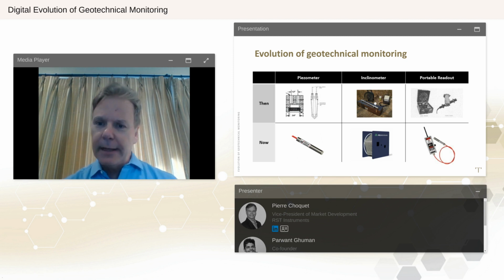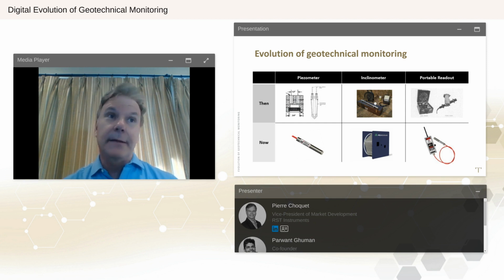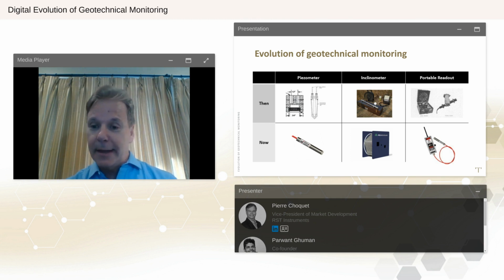Then in 1979, I became part of the monitoring team as a graduate student of the 13-kilometer long, 8-meter wide Frejus tunnel built in the Alps that was under construction between France and Italy. And I'll tell you that I would have liked data loggers to be invented at that time, because I had a good 50 vibrating wire concrete strain gauges and piezometers to read every day, in addition to measuring convergence across the 8-meter diameter using a tape extensometer. By the way, I would have also liked it if Excel had been invented at that time, because I had to plot all that data by hand for my daily and weekly reporting.